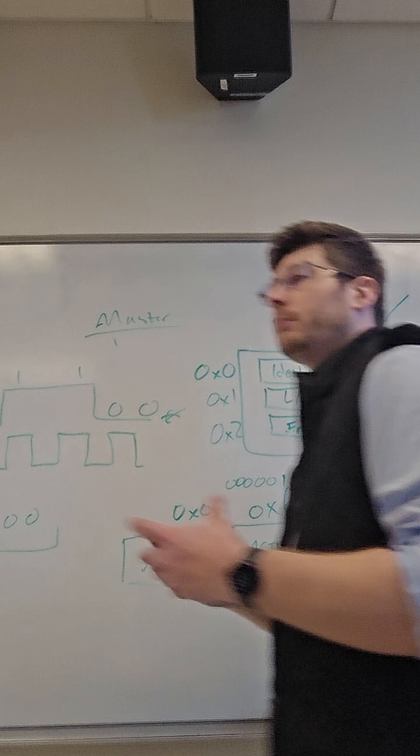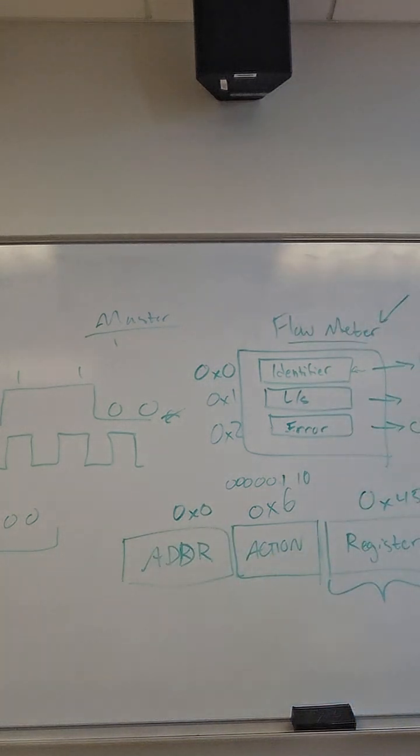When we design PLC to PLC communication, we set up the registers too. So you would have a structured text that would set up, this is register 1 and what information goes into here. This is register 2 and what information goes into there. And then that way, when one PLC requests from your PLC, hey, what information is in register blah blah, it will yield that information through software. Okay.